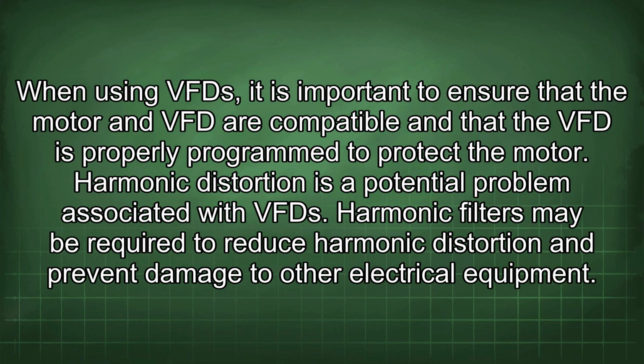When using VFD, it is important to ensure that the motor and VFD are compatible and that the VFD is properly programmed to protect the motor. Harmonic distortion is a potential problem associated with VFD. Harmonic filters may be required to reduce harmonic distortion and prevent damage to other electrical equipment.